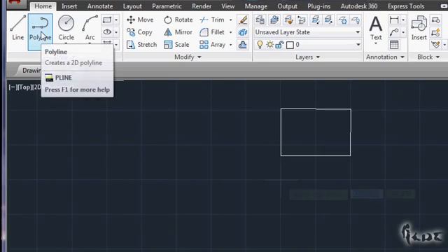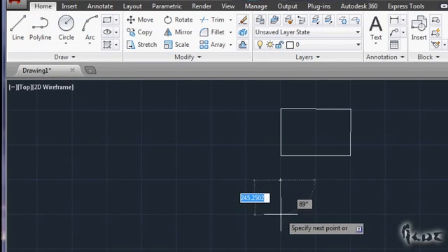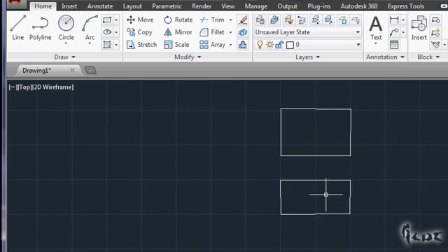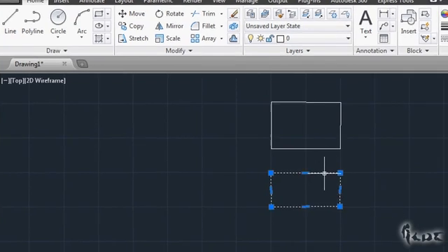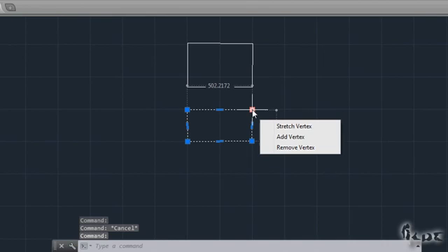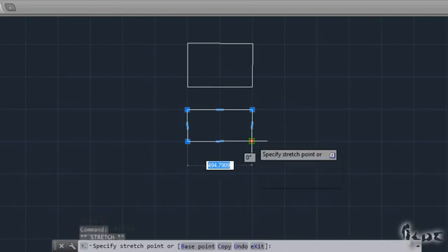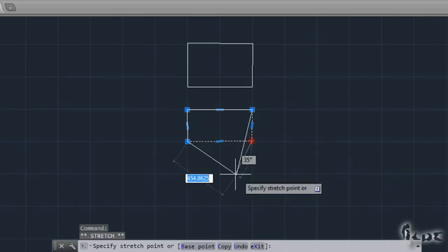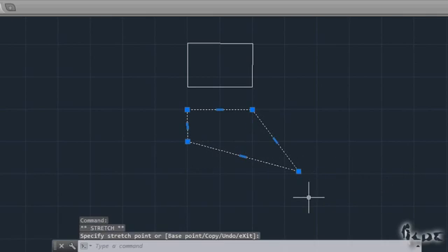Different is the polyline. When you create the same polygon with a polyline, the selection is made on the whole polygon, because it is composed of one single polyline object. Click on the polyline to start editing it. It will have squared points and small rectangles on each side that you can use to edit your polyline properly.